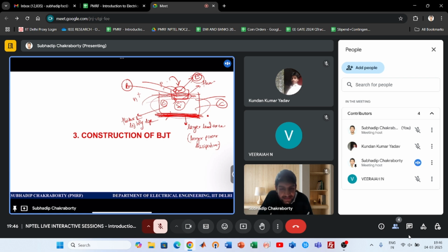In other words, even if you do not damage the device, placing a smaller amount of voltage at the collector, which is the output, thinking it to be the emitter, because you interchanged emitter and collector. So actually VC is more than VB, get it. Now interchanging the two, I told you, the emitter is placed only to initiate the process, and then the collector will seek those high number of charge carriers. But if you interchange, then you would place a larger voltage in the emitter base bias, which will damage the junction.